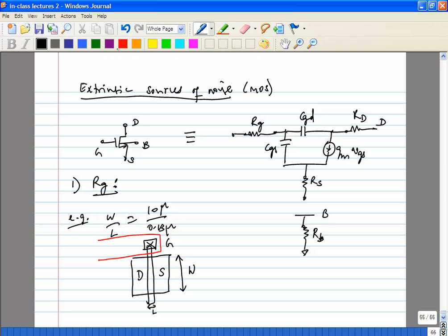So let's say this is the poly, this thin rectangle here. So what will happen is, your transistor is actually a distributed structure, because your gate signal is coming in from here and it's traveling all the way down here. So you're lumping it as a lumped resistance Rg, but this is the overall transistor, so you're going to have some poly resistance associated with it. How can you reduce this resistance?